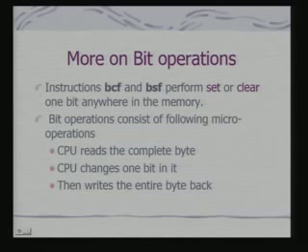We shall discuss this problem when we discuss the peripherals, that is, the digital I/O ports supported on PIC. But this read, modify, write is again an atomic operation. The advantage of the atomic operation is that it cannot be interrupted by an external interrupt.